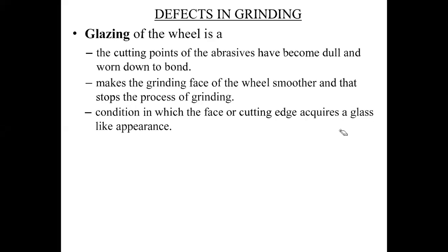Similarly in grinding, the fine particles that are placed on the grinding wheel wear out after some time. Normally that wear rate in grinding is very fast compared with any other cutting tools we discussed before, whether it's milling, turning, or drilling. Because here we have very small particles. It's not a big lump of material like your drilling bit, your milling cutter, or your lathe cutter. It is a grinding wheel.